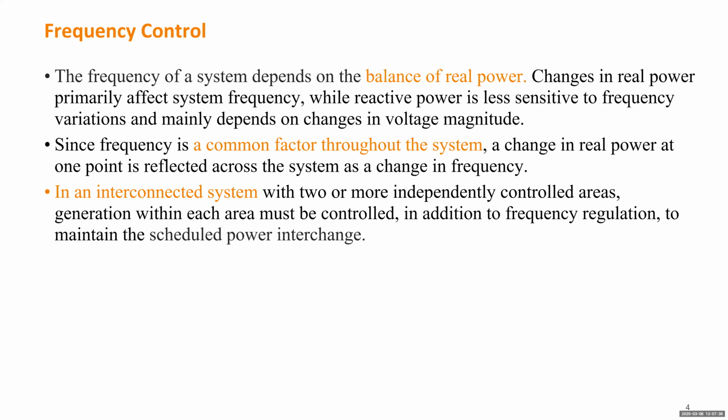That area in the US is called a balancing authority. Remember we talked about balancing authority. A balancing authority is the smallest region where you need to keep the real-time balance of active and reactive power. So for each balancing authority, you need to have at least one generator which can do the frequency control, which means it has regulation, a governor, and you need to connect it to the automatic generation control system.